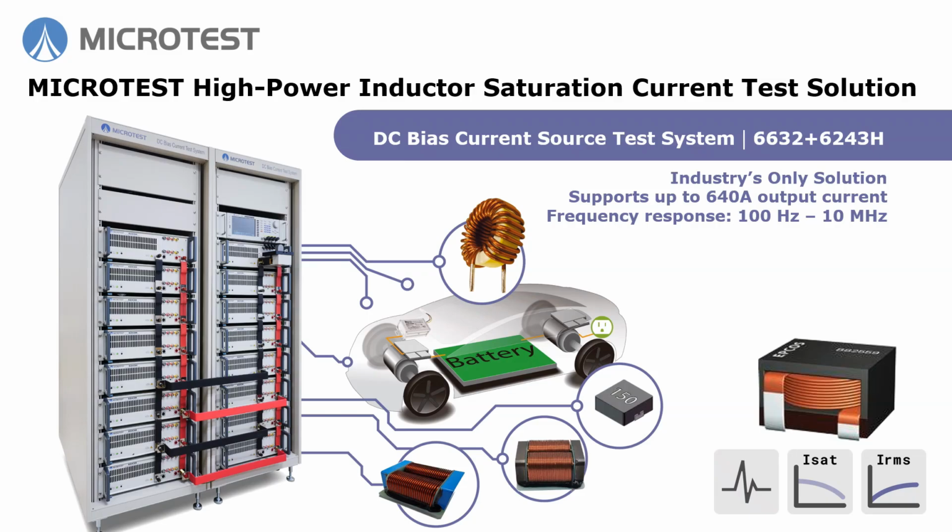In high-power power supply design, magnetic saturation can cause inductor failure, drop system efficiency, or even damage components. That's why understanding an inductor's saturation current and thermal rise is key to stable and safe circuit design.